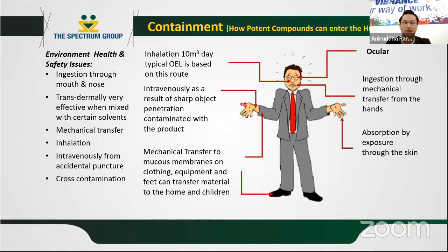Here, one point: all of our containment calculations are based on the assumption that we inhale 10 meter cube of air per day. That is the average we consider, and based on this, an operator exposure limit is set, which is the maximum an operator can inhale.